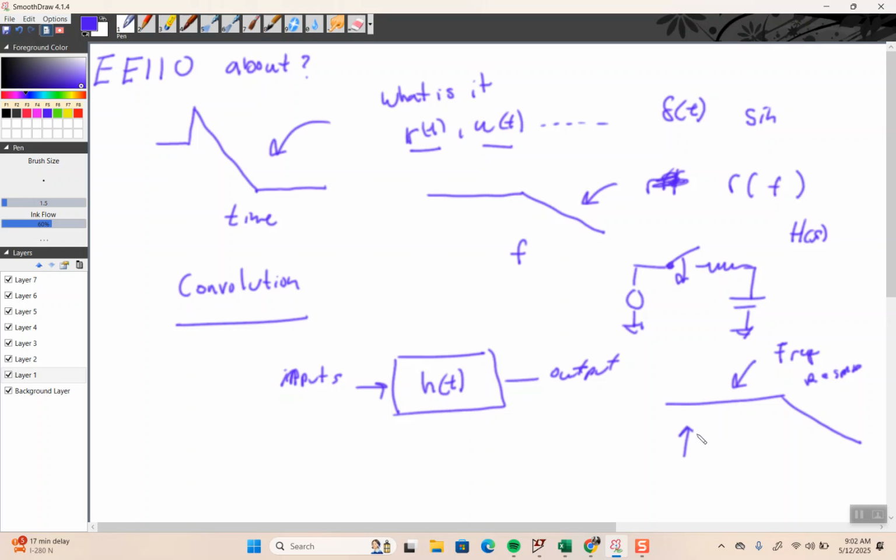But you would just put in different frequencies, measure the magnitude and the phase, and come up with that, right? So it would all happen here, where I would put in a sine, use convolution, right? And measure an output and get an attenuation factor and a phase factor. And I would just step this, I would make a table and go through that.